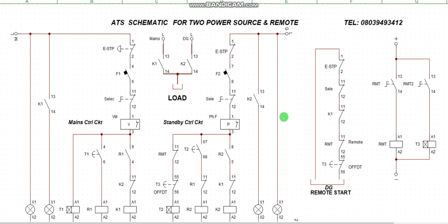Okay, let me repeat again. The control panel that is going to communicate with this cable, with this particular logic, is expected to have a cooldown duration of 3 minutes. That means each time I operate any of this to cut off the remote signal or to cut off the start genset, to shut down and also shut down the contactor, the genset will still be running for 3 minutes. That is to cool down, to stabilize the moving machineries before it finally shuts down. That same minute is also applicable when the genset is put on, when it starts, when the genset comes up.